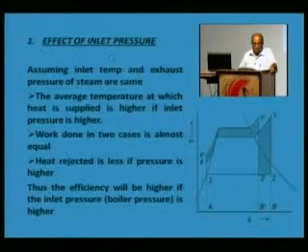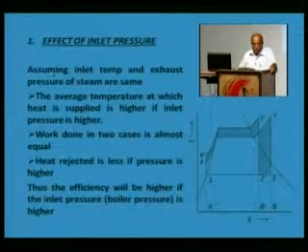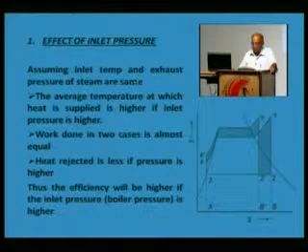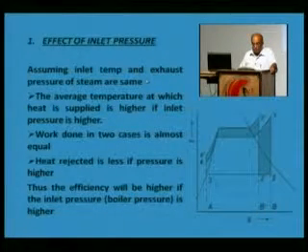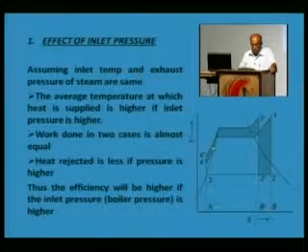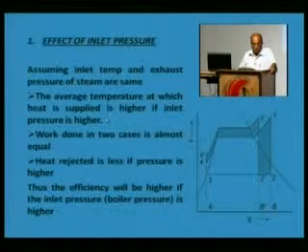Let us study the effect of inlet pressure. We assume that the inlet temperature of the steam and exhaust pressure of the steam being the same in the two cases, if the pressure is increased, we can see that the average temperature at which heat is supplied is higher if inlet pressure is higher.